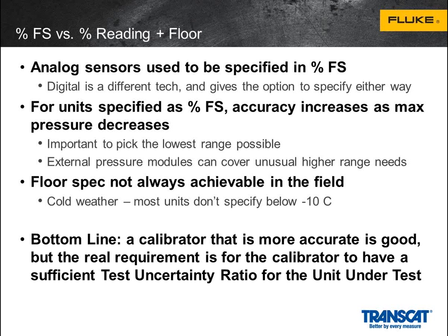So for percent full scale, as we discussed, because the error relates to the full scale value of the unit, basically you want to pick the lowest possible value that you can get away with. And what we'll frequently recommend for people who are looking at a unit like this is to pick the unit that is at about 80 to 90% of the work that you do.